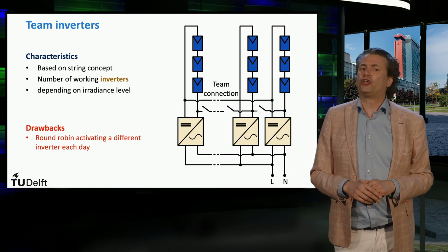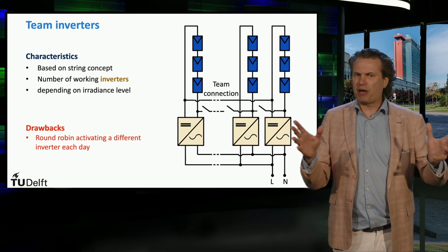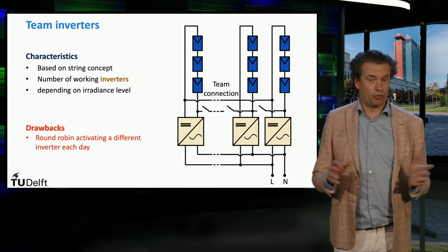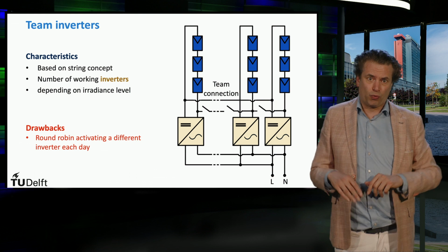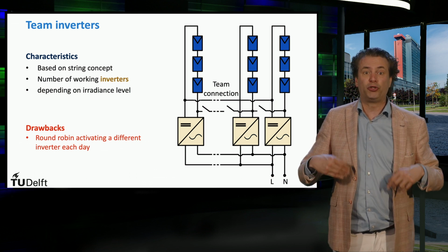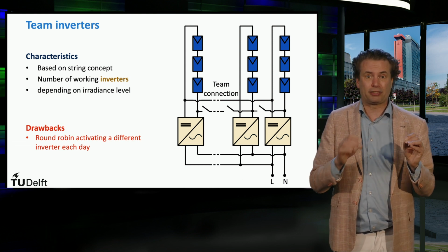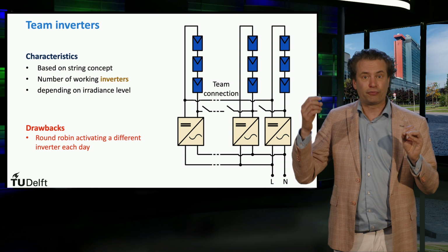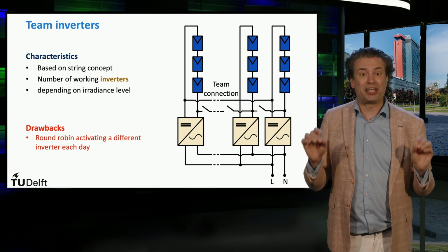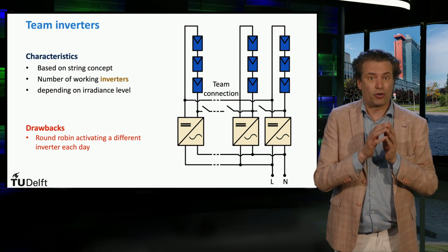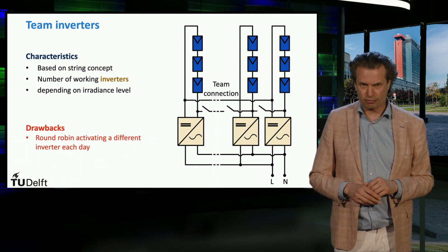Finally, based on the string concept, we have the team inverters configuration, suitable for places with variable meteorological conditions. Basically, it's a combination of several string inverters working with the team concept to reduce the overall losses, as any power electronic converter is designed such that its maximum efficiency is near full load. The concept of team inverter is that each string is connected to a bus that is activated or not depending on the amount of power that the PV modules are generating.